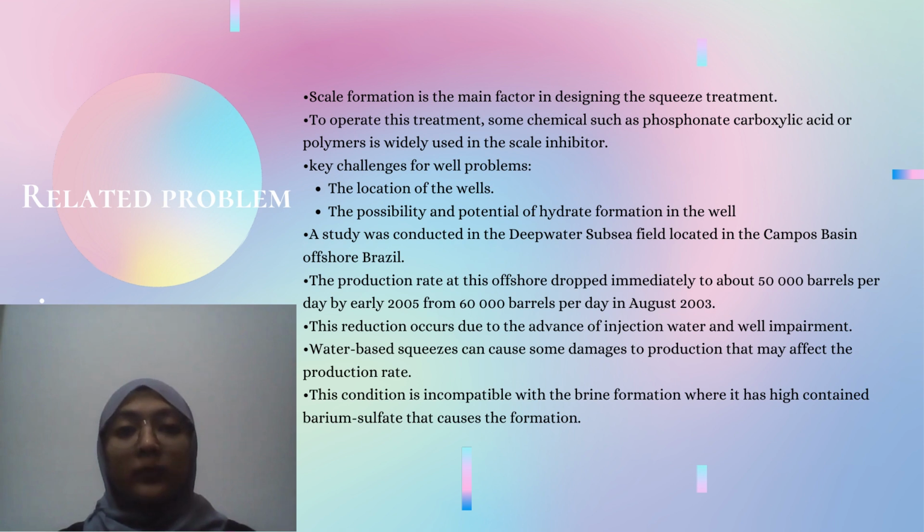Next is the problem related to scale inhibitor squeeze treatment. Scale formation is the main factor in designing the squeeze treatment. To operate this treatment, some chemicals such as sulfonate, carboxylic acid or polymer are widely used in the scale inhibitor.